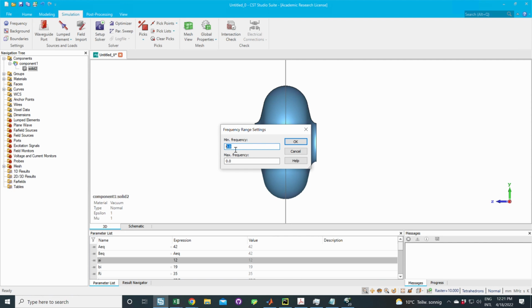Once you generate your mesh, the matrix is usually large, so we just want to target the frequency so that it reduces the computational time. So I could select just a band around 1290 because I'm interested in 1300, and I'm just interested in one mode.